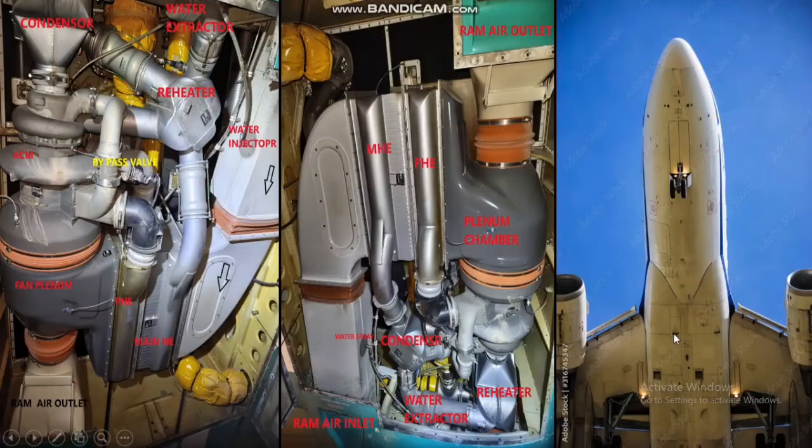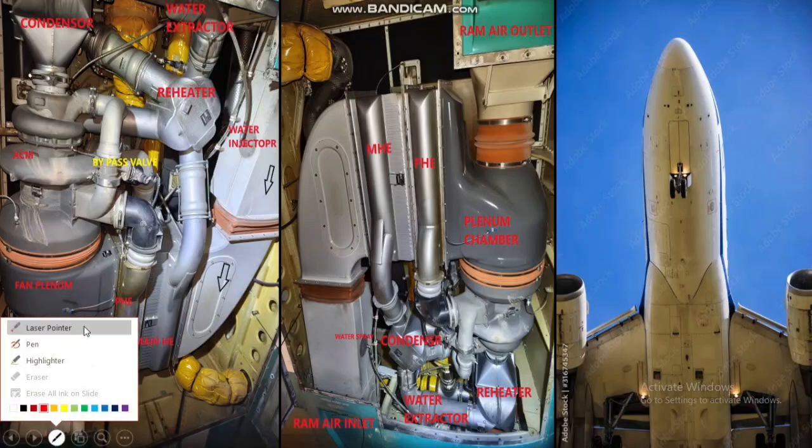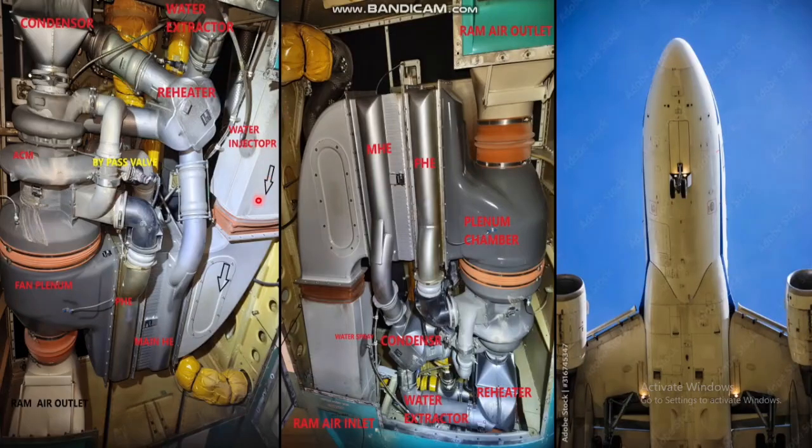This is your inlet area of the pack. This is the exhaust area of the pack, and you will see the air inlet area is this, and this is your bypass valve. This is your air cycle machine. This is your fan plenum chamber. This is your main heat exchanger. This is a primary heat exchanger. This is your reheater. This is your condenser. This is your water extractor. So these are the components.